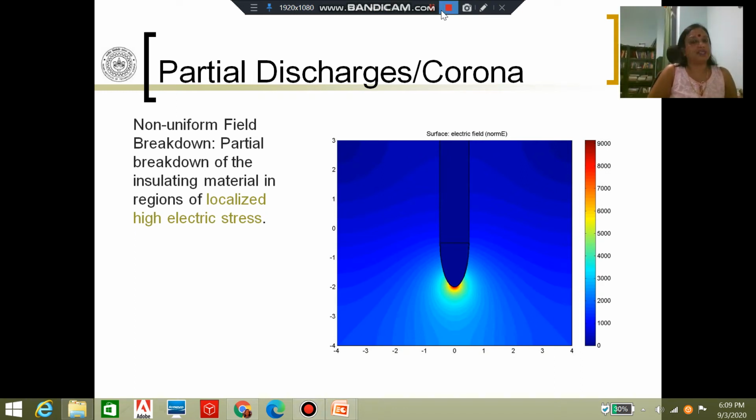So far we have only constrained ourselves to talk about breakdown under uniform fields. But what happens when a gaseous medium is present and a non-uniform field is impressed on it? When you have a non-uniform electric field, the situation is quite different from uniform fields, and therefore the breakdown in a non-uniform field is hardly likely to be due to processes similar to the Townsend mechanism or the Streamer mechanism. Something very different is likely to happen.